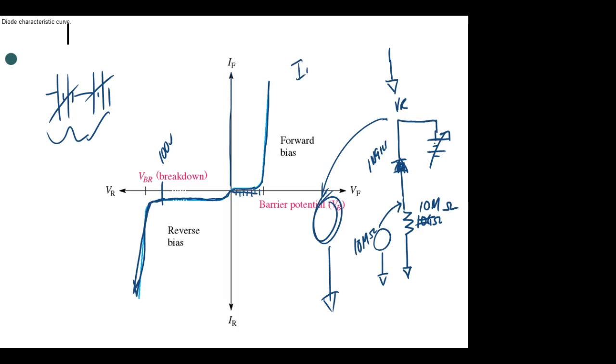So what is I equal to? V over R. So if we know the size of this resistor and we measure the voltage drop across it, we can calculate the current flow through the resistor. And the resistor is in series with the diode. And what's the same in a series circuit? Current. The problem is that we can't use 10 megohms when we calculate that current.